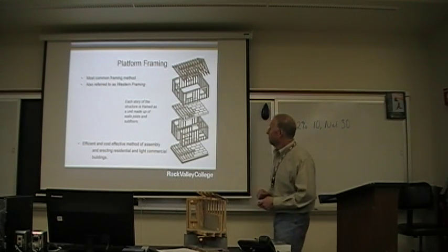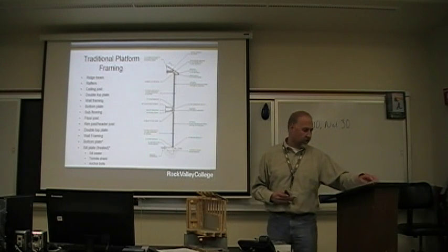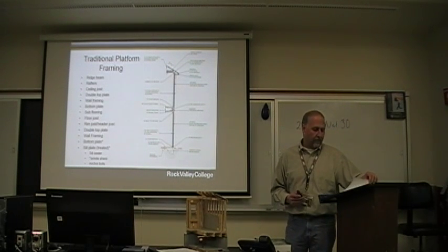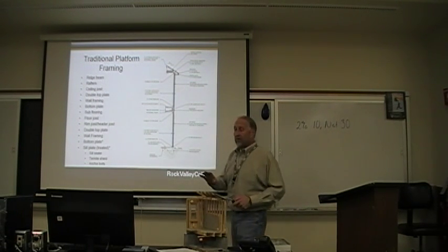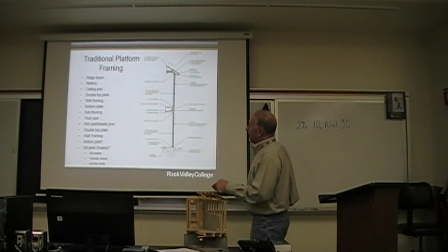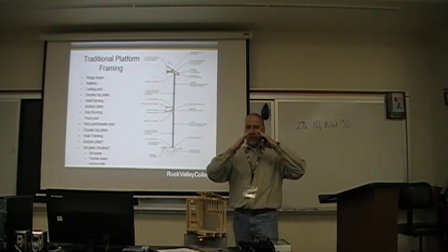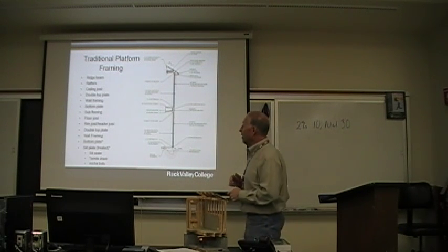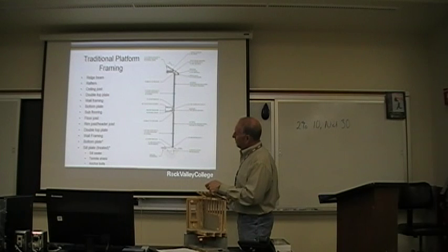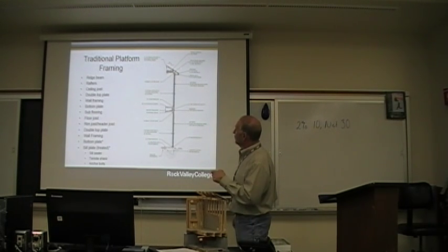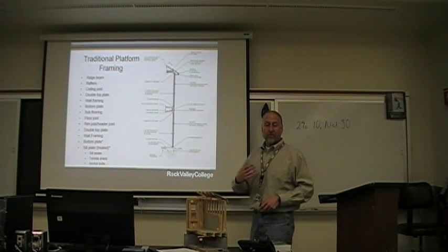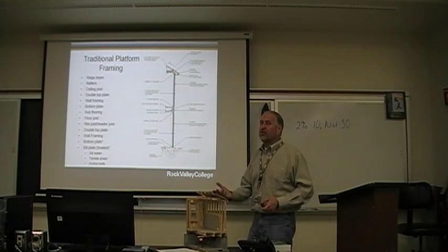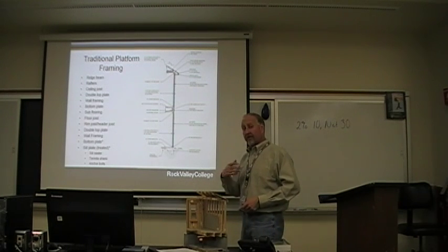Okay, let's move on. So here's a typical wall section for a wood frame structure, platform frame structure. Now I know it's a little difficult to read, but I'll walk you through it. Starting at the top, working down. We're looking here at where our roof rafters meet. We have a main support up there. We call that a ridge beam. But this assembly here, our ridge beam, our rafters, which this is our rafter here, and our ceiling joists, we either stick build, or build on site, or what's most commonly used now, we use truss systems. So truss systems really have come on board.